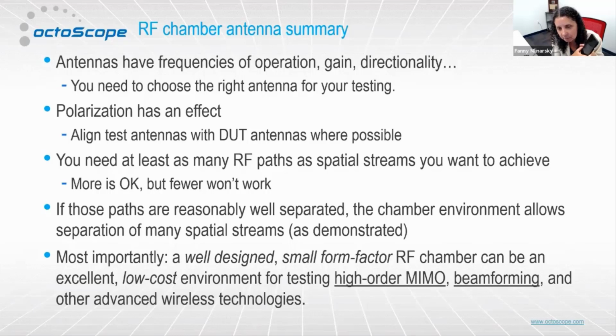It's a common trick in a small device, an IoT device or a phone, to cross-polarize so that you can get multiple streams. Regarding OFDMA, you get multiple streams by virtue of phasing and frequency offsetting, so you don't need that diversity to put multiple devices on the link. But for MIMO you do, and it's a common trick to use polarization to get more streams. Yep, exactly. That's true for MIMO.